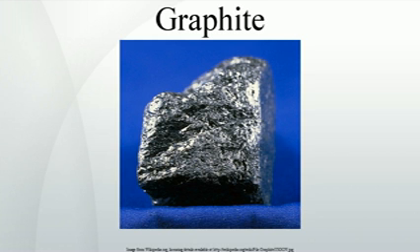Powder and scrap. The powder is made by heating powdered petroleum coke above the temperature of graphitization, sometimes with minor modifications. The graphite scrap comes from pieces of unusable electrode material, in the manufacturing stage or after use, and lathe turnings, usually after crushing and sizing.